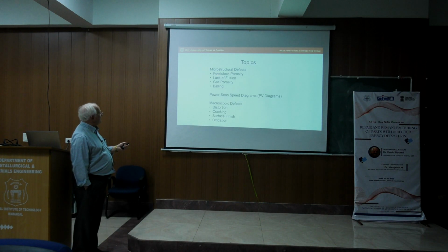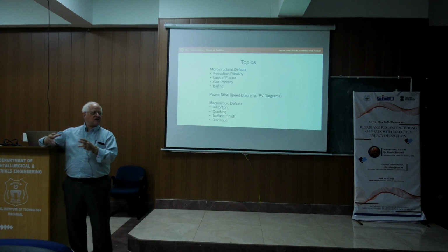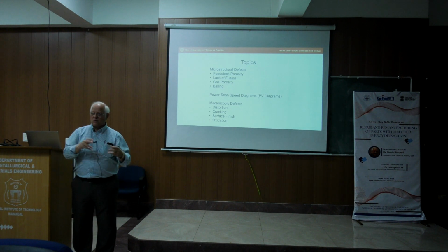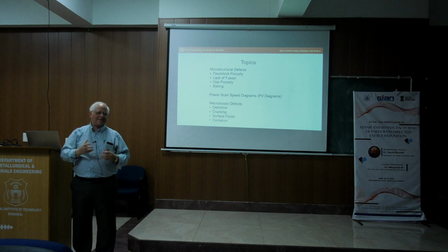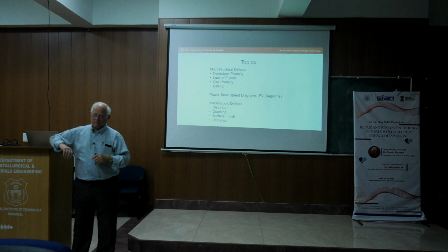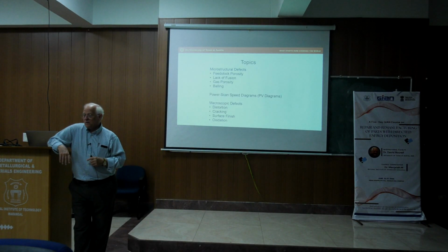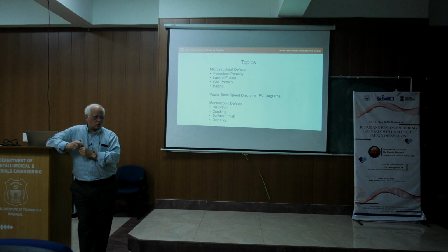So we have feedstock porosity. This is basically porosity that exists in the feedstock and which continues during the processing and is manifested in the part. The classic example of this is, it was sort of an eye-opening experience about 10 years ago when a group, I guess it was Tony Rollett at Carnegie Mellon, was the first person that I saw present this work.